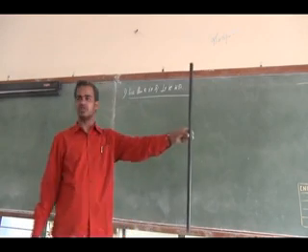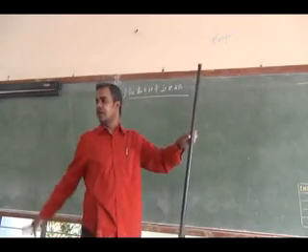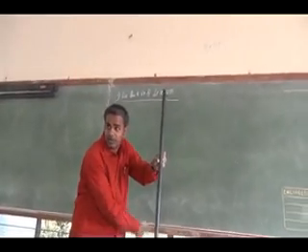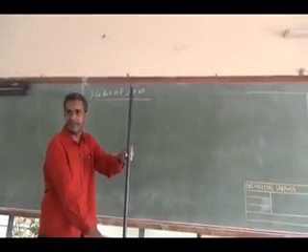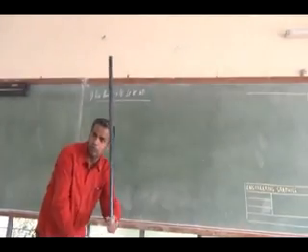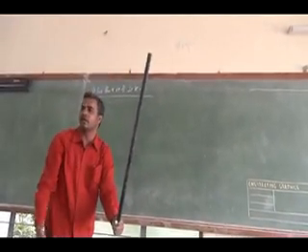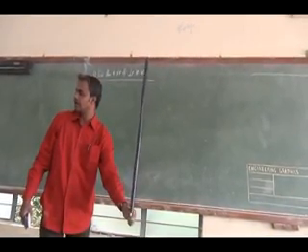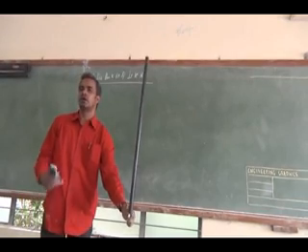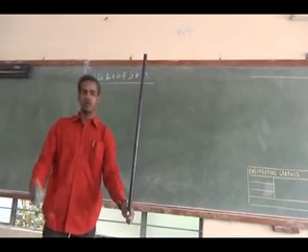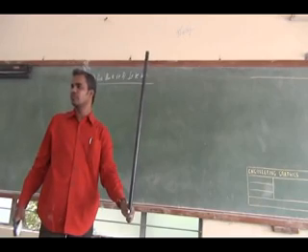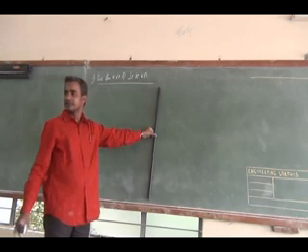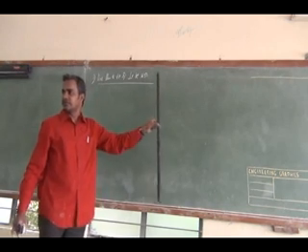You can see here, this is the orientation, this is the line having length 50 mm and the end A is here. So it is 10 mm above HP and 15 mm in front of VP, okay, the end A. The line orientation could be like this, but it is given that it is parallel to VP and perpendicular to HP. Right. So you are asked to draw the front view and top view. What will the front view be? A straight line, I can see it as it is.